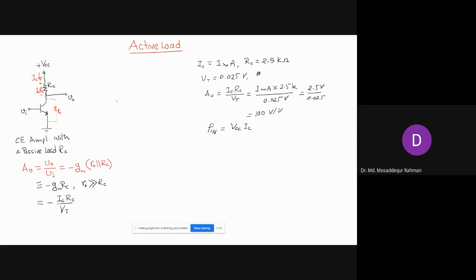That is the power being supplied to this amplifier by the power supply, and the higher you take this voltage, the more power the amplifier will consume. So one design aspect of the amplifier is to keep VCC as low as possible, the minimum needed for the amplifier to work properly for the whole range of the signal.